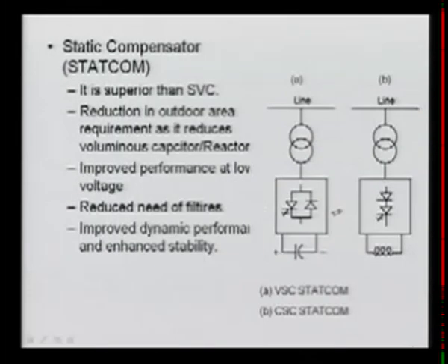So it is superior because we are using converters here. There is a reduction in the outdoor area requirement, it requires less space. It reduces the voluminous capacitors and reactors. There are so many inductors and capacitors that were used. Here we require only one capacitor or inductor that will serve your purpose. So that's why we require less space as well.